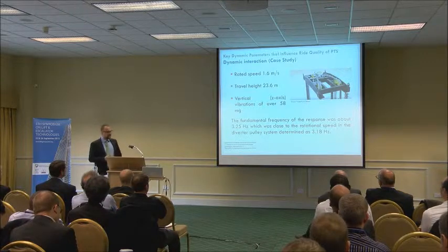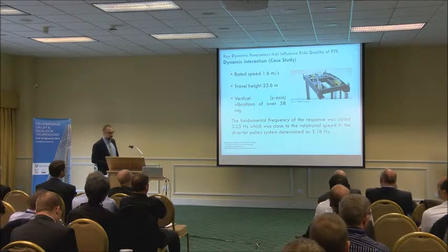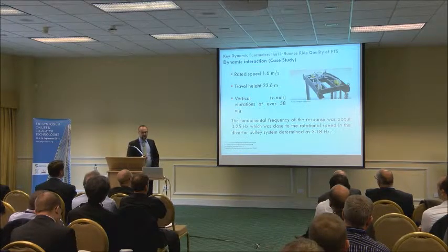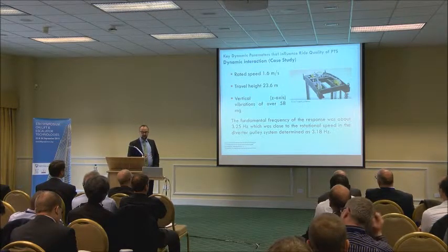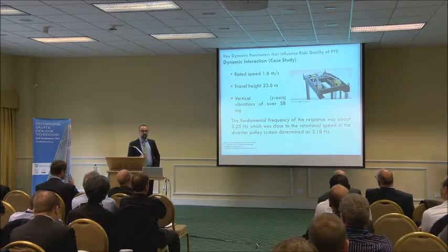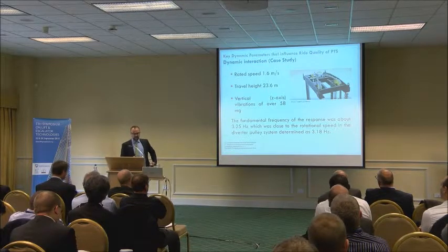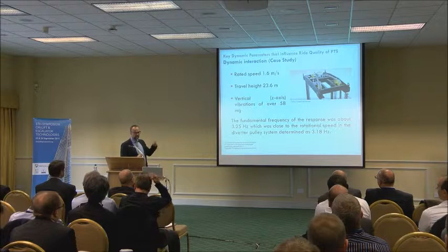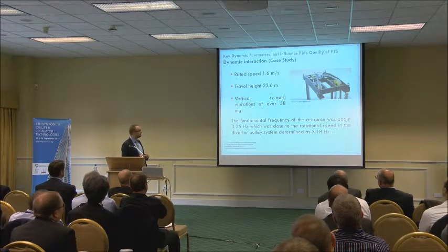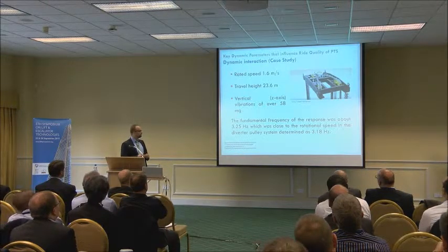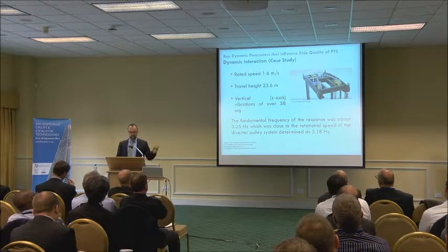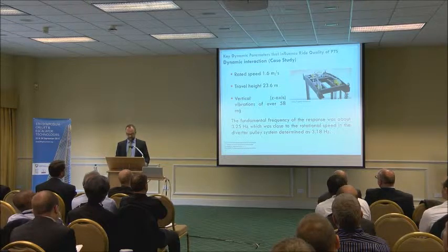The investigations we did together with the University of Northampton have shown that the fundamental frequency of the response was about 3.25 hertz, which was close to the frequency of the rotational speed in the diverter pulley, which was determined as 3.18 hertz. By the way, this was a 4-to-1 rope system.